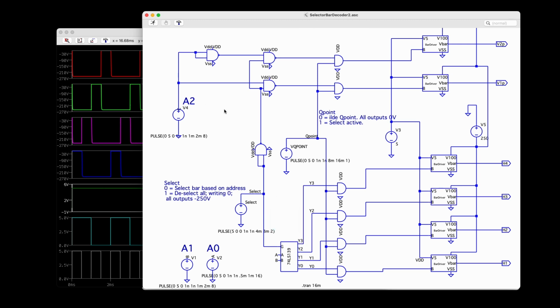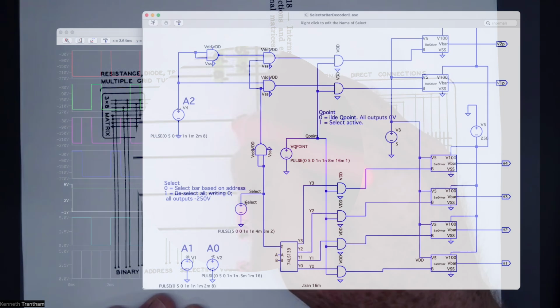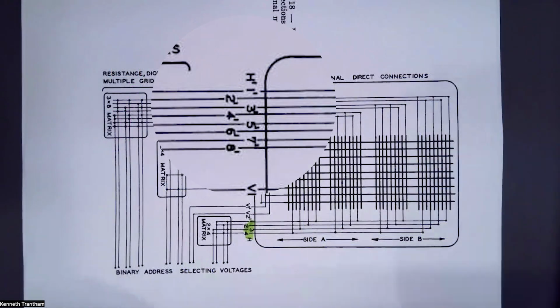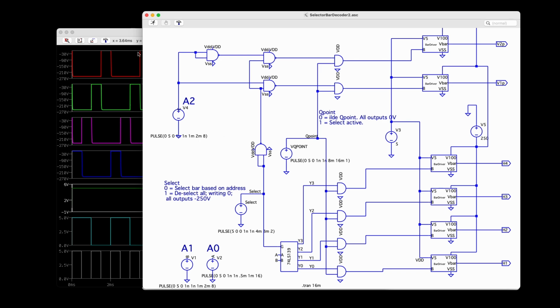The A2 bit is a little different. Essentially what I have here is a 1-bit to 2-line decoder with the same sort of gating involved. The other more significant bits, I've got another 2-bit to 4-line decoder for the V group 1 through 4, and then I've got a 3-bit to 8-line decoder for the H prime group. But conceptually it's all the same as this.